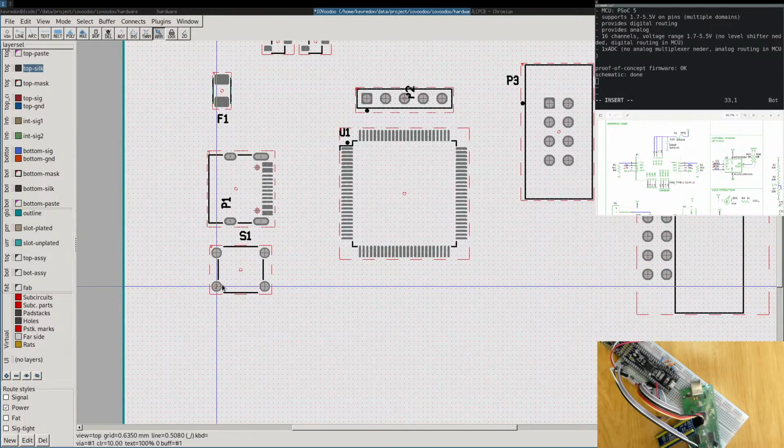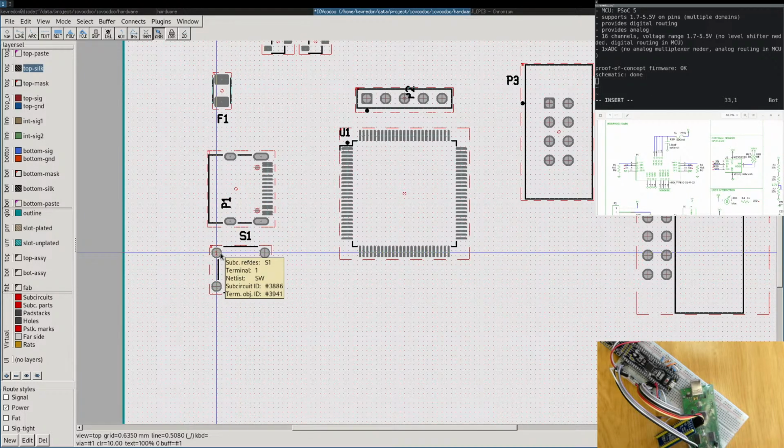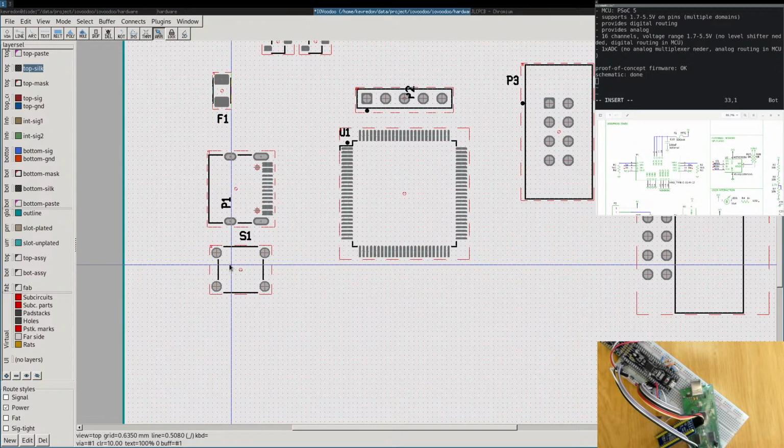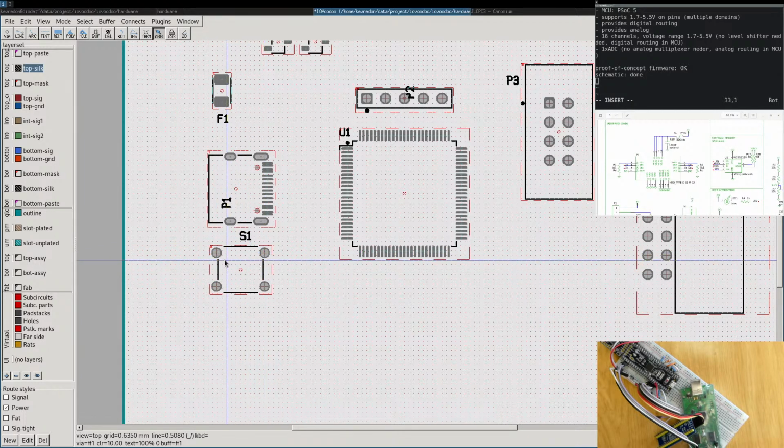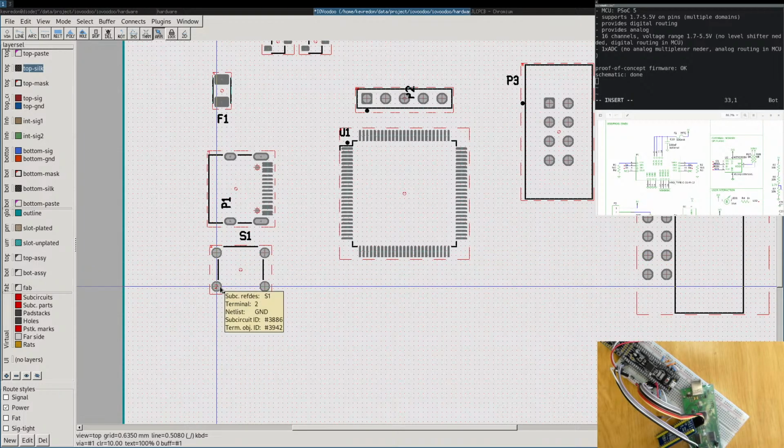This is pin 1. These 2 pins on the buttons are really a pain. These buttons are double row, double terminal, DPDT, double pole, double throw. So you have 2 switches in there actually, but I never know. I think these 2 pins are connected, these are not connected. I'll check that. I always forget.